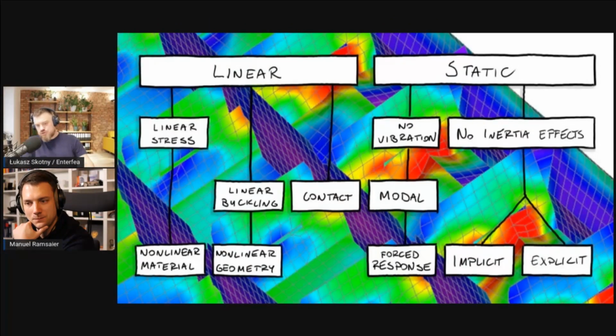It's good to remember that if two things are touching, connecting them might be a mistake. Because if a book is lying on the table, it's not welded to the table. You can pick it up. Frozen contact, sure, if you push it against the table, it seems welded, but if you try to lift it up, it's very easy. So just modeling things as welded because they are touching is often very misleading, and also a highly common beginner mistake, I would say.